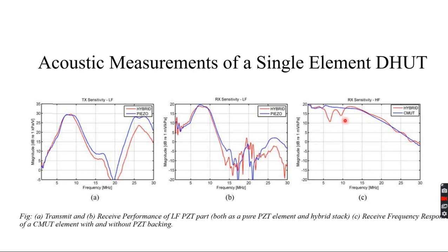Although there have been some efforts reported in the literature. For example, researchers have introduced interlaced or interleaved architectures in which the two transducers don't share the same footprint, so you don't have this coupling. But if it's the same footprint, it can still be reduced by using materials like silicone or RTV rubber, in which, because of the attenuation, the peaks go down a bit, and they're also shifted down in frequency, affording more bandwidth. There has been some effort by some of the people in this group, and I've seen how to reduce this problem.